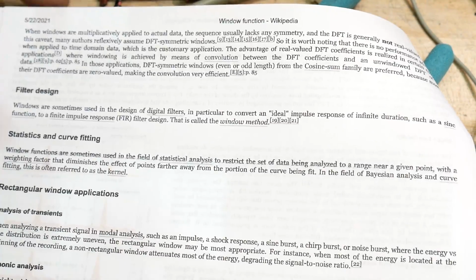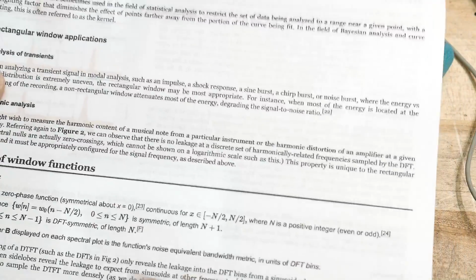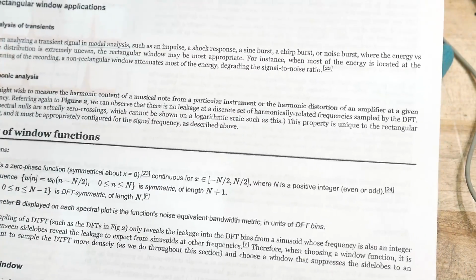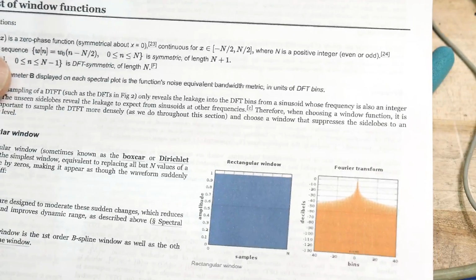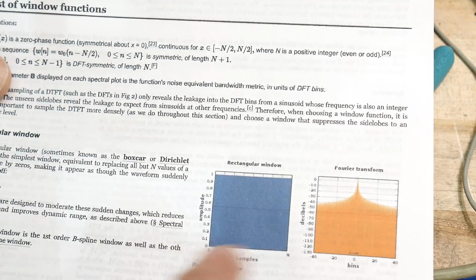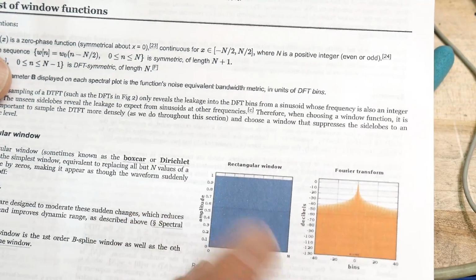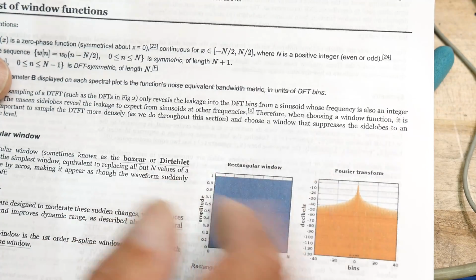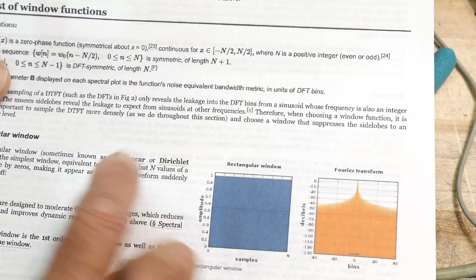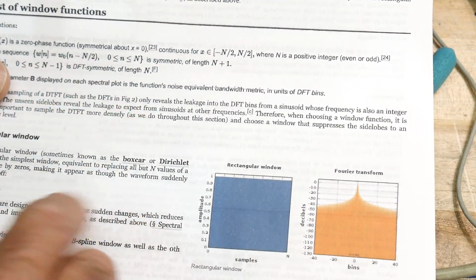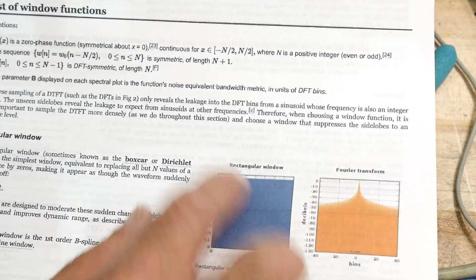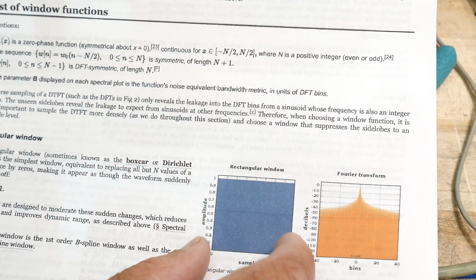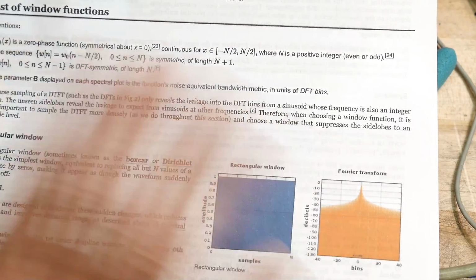It's really well done. So here's a list of window functions. Okay, so what is a rectangular window? A rectangular window says with n number of samples, treat all samples equally. Just sum them up. This is like an average, right? Also called boxcar averaging. You may have heard that term, boxcar averaging, which is just whatever's in the box, add it in, and that's all there is to it.